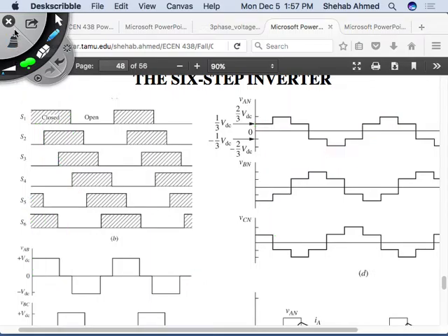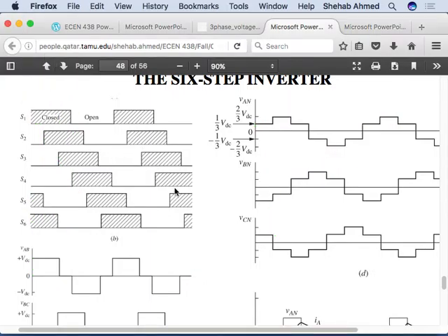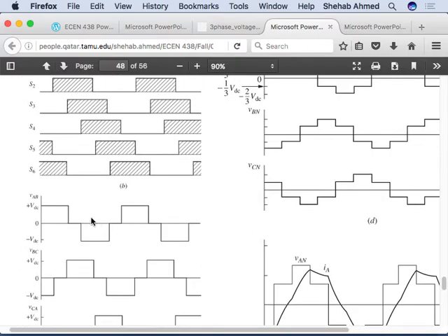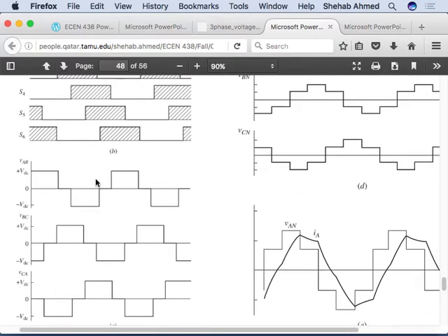Okay, so this is the simplest three-phase inverter. What do we get here? We get exactly the single pulse per cycle type waveform that we saw before for the single-phase inverter, right? And why did we want to go away from that? We went away from that because it produces output power quality that we don't like, right? But this is a way to get three-phase output. The 6-step operation of a three-phase inverter is the simplest way to do it.